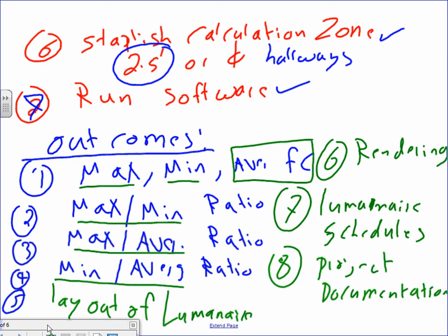You take all your fixtures, after you do the calculation, into a drafting software like CAD or Revit. We're doing Revit. We took it to CAD, and from CAD imported into Revit. We lay out our fixtures in 3D into that model. We circuited all these fixtures. We switched all these fixtures, high voltage or low voltage or occupancy sensors or whatnot. And we tagged these fixtures with the fixture type, the switch that's going to switch the fixture, and the circuit that's going to power that fixture. And hopefully they'll pay us when we submit our product. Here's your lighting layout and circuiting.